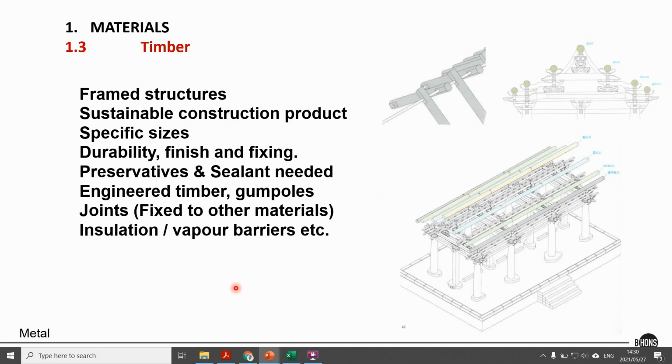Then also remember, you can work with gum poles. Often we use that. Gum poles are quite robust materials, also a bit more affordable. But remember, you can't necessarily specify the size of a gum pole accurately because gum poles taper. And that means also in the joint, you have to allow for that flexibility of having a thinner and a thicker gum pole. And so we often allow gum poles to overlap and extend beyond an edge, and you've got layered processes of fixing it together, and you use threaded bolts often to deal with the different depths in the end.